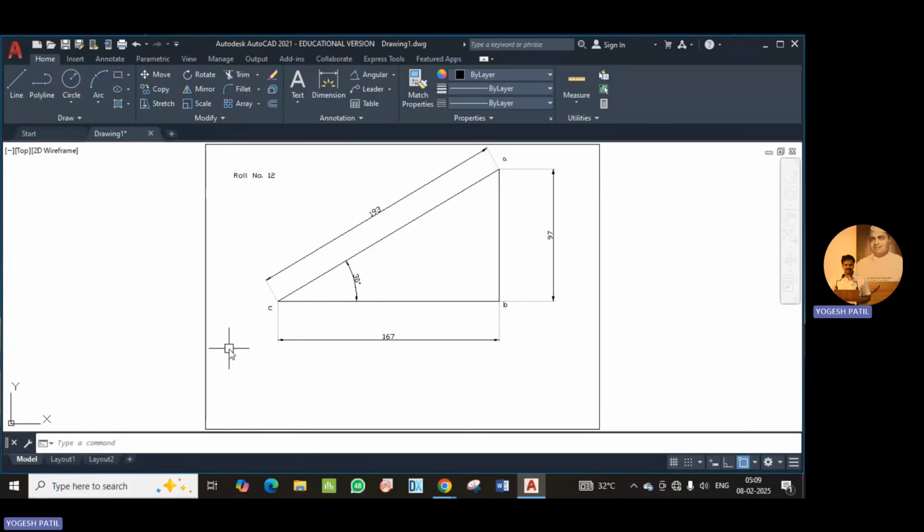So for the DT command we have to use the text size as 3.5, the angle of rotation as 0, and we have to click somewhere to open the text box. These are the basic settings that we should do while using AutoCAD.